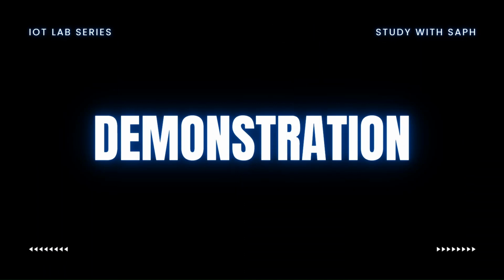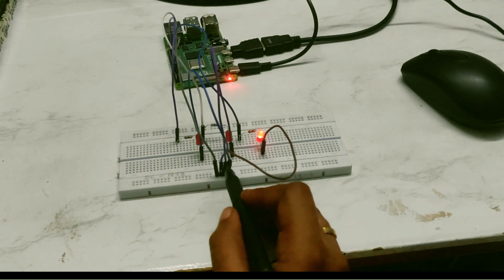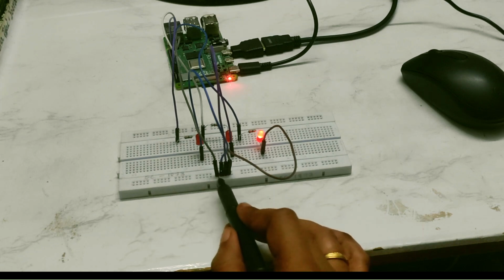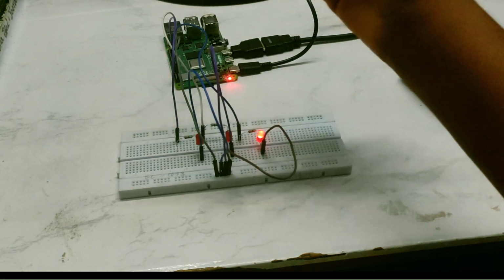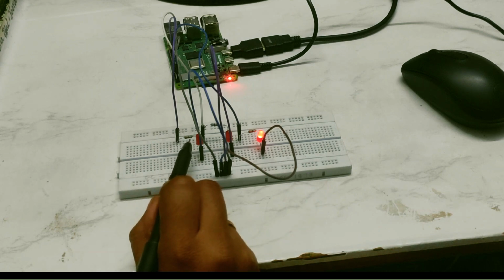Now, let us move on to having a look at the live demonstration of the experiment. Connections have been made as per the circuit diagram. We first have the gray wire, which is connected to the ground terminal on the Raspberry Pi. The adjacent slots are internally shorted, hence all of them represent the ground voltage level itself. Actually, we had to connect each of the cathode ends of the LEDs to the ground pin on the Raspberry Pi. However, this would lead to extra connections. Instead, just by connecting the wires to the breadboard, it will represent the same voltage level.